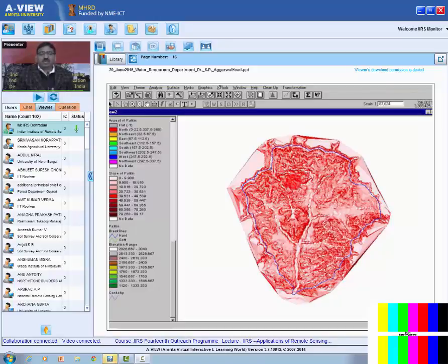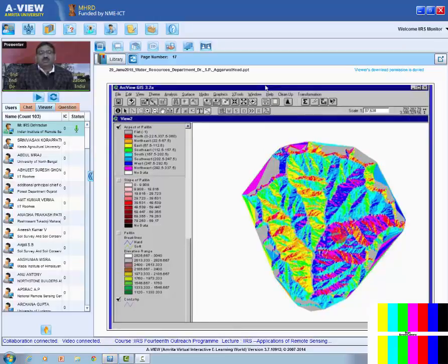This is also required for hydrological modeling. Why is it required? Because water follows the slope. Water moves from high point to low point. So DEM and slope are necessary along with the flow. The next step is we calculate the flow direction or aspect. What is the aspect or flow direction? How water will move: from the north direction, south direction, east direction. So we calculate using this model.